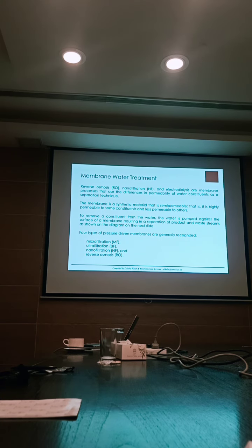So that brings us on to membranes, I suppose, if we're okay with the concept of ion exchange. This is just talking concepts, by the way. So in our desire to start removing salts, we went back to basics, I suppose, in osmosis and reverse osmosis. And we quickly realized that if we use a membrane that's got very small openings in it, and we apply pressure on that, we can force the water through the membrane and leave the contaminants behind.